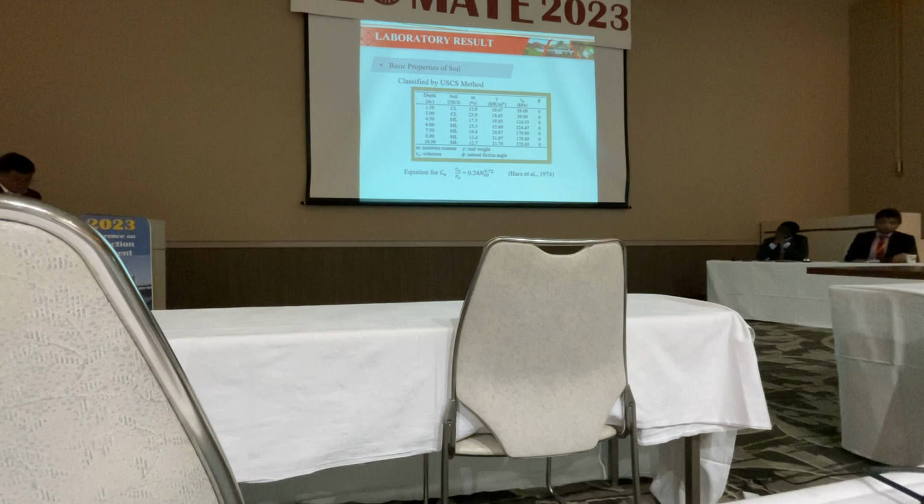The depth of 1.5 to 3 meters is about 40 kPa. Then it goes up to about 225 at 6 meters and drops to 180 kPa at 7.5 to 9 meters, and 325 is the maximum at 10.5 meters. Phi equals 0.